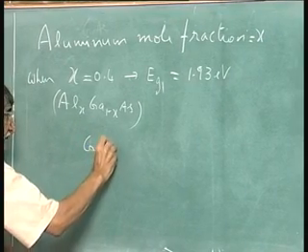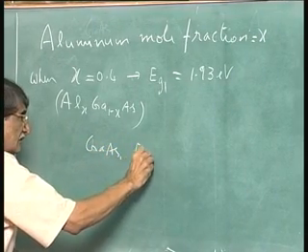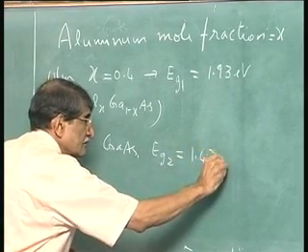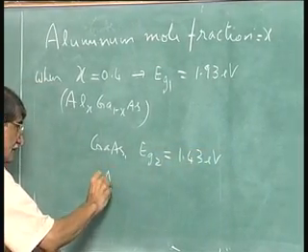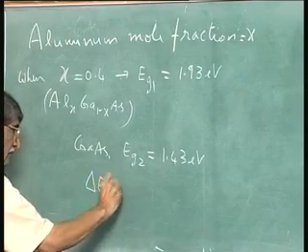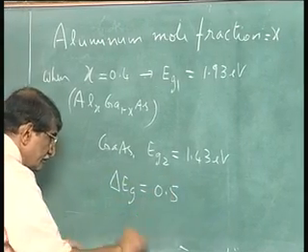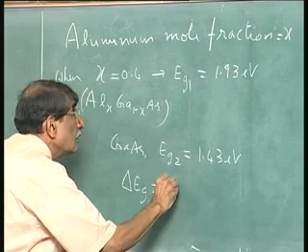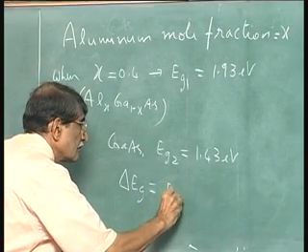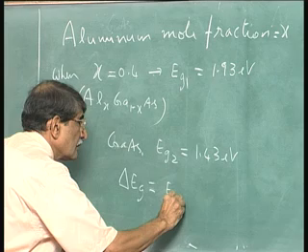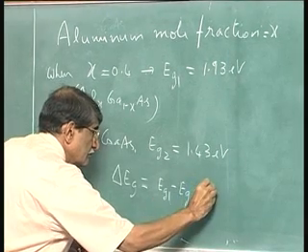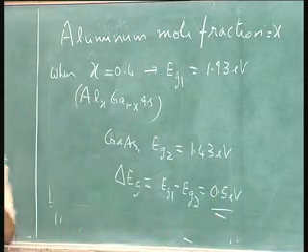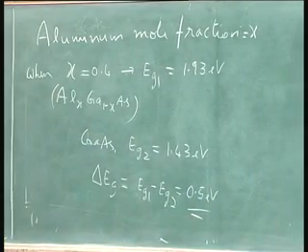I will go back to that previous slide. Delta E g is 0.5 electron volts at x equal to 0.4. In fact, to get that, I put that diagram for you, because if you just draw straight from 1.8 to that diagram, you won't get that. Now, what people have observed needs a little bit of explanation. A qualitative understanding we will try to get.